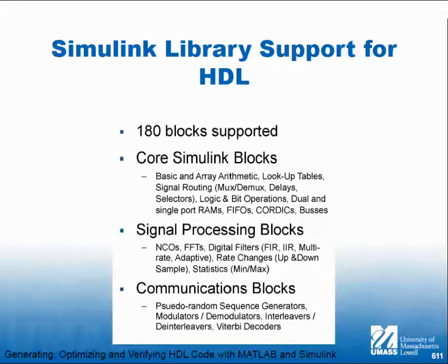I find that it's easier for me to design directly with the Xilinx. So instead of putting in an FFT in MATLAB, I can put in an FFT right in Vivado. And if I have a complicated design, instead of having a huge picture that I have to navigate across to make these connections, I'm more comfortable just creating hierarchical HDL. And it comes out better.